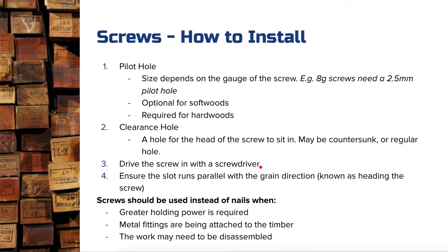Now, screws should be used instead of nails in these occasions: when there is an enormous amount of holding power required compared to what you'd use a nail for. If you're attaching metal fittings to timber, like a hinge to timber, for example, or if you think the project may need to be disassembled at some point. If your project doesn't need to be disassembled, then you might as well use a nail, because generally speaking, they're just that little bit cheaper, and you don't need to go with the pilot holes, clearance holes, etc. Okay, so something to think about.